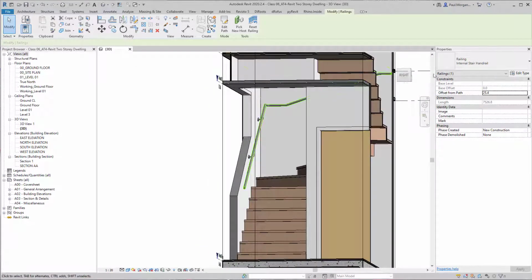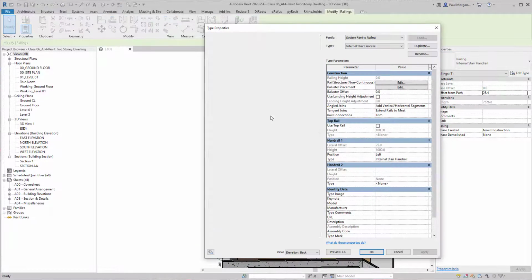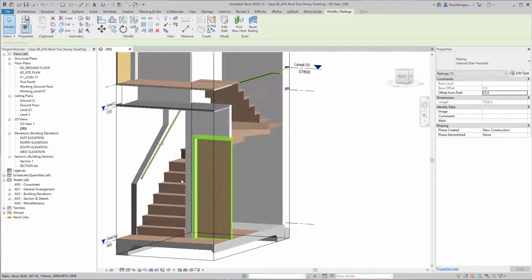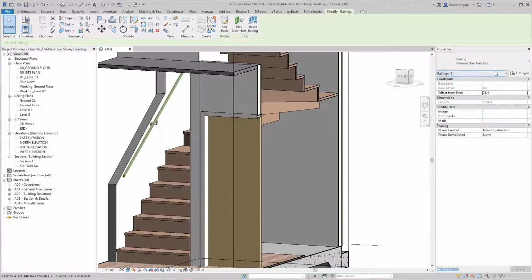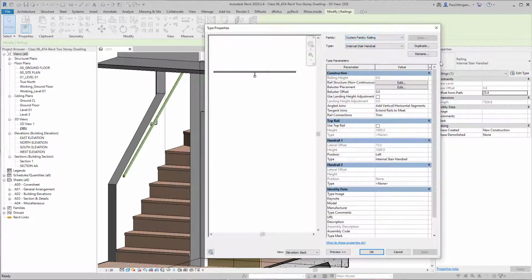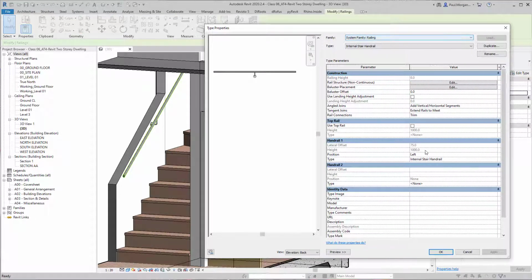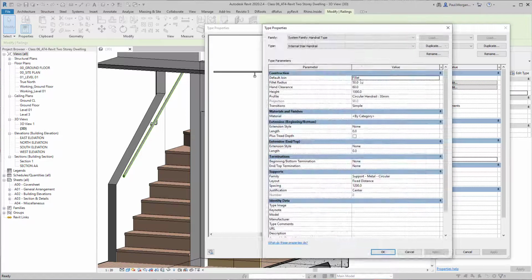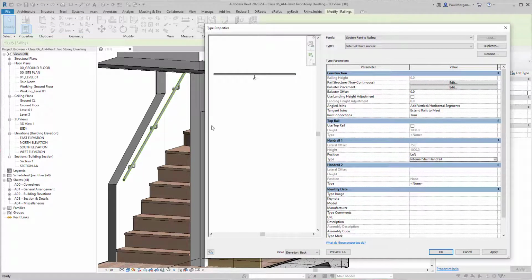All right, next up, let's go back to that handrail again. I'll move this across so it looks like this, so we can keep an eye on that handrail. Okay, and then let's take a look at some other things. So internal stair handrail, let's change the support distance to say 800. So you'll see there's more supports periodically. And the height, let's go from 1000, let's make it 950. Yeah, let's say 950. Okay, all right, that looks good.